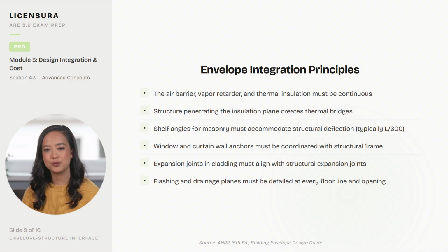Pre-bid substitutions before the bid date are communicated to all bidders via addendum if approved. Post-bid or pre-award substitutions after the bid but before the contract require careful review because they may affect bid evaluation. Construction substitutions after contract award require formal submittals and architect review. VECP substitutions during construction require cost analysis and a shared savings agreement between owner and contractor.